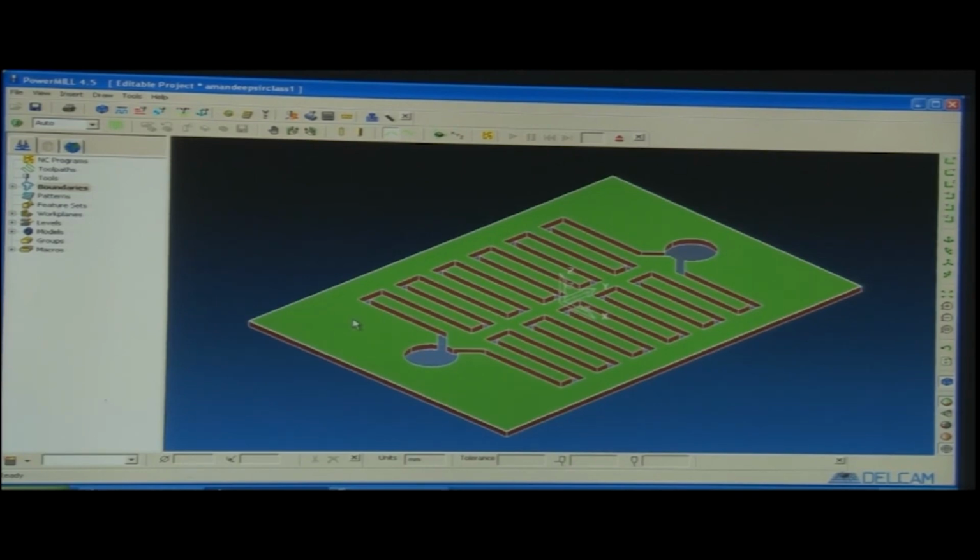Normally, when we generate the code, it is important that we take care of the movement of the tool in the XY direction as well as in the Z direction, because if anything goes wrong, the job will definitely go bad, and the tool can also go blunt. The tool can also break, and big accidents can also happen. So, it is very important to run this simulation before going to the actual machining in CNC.